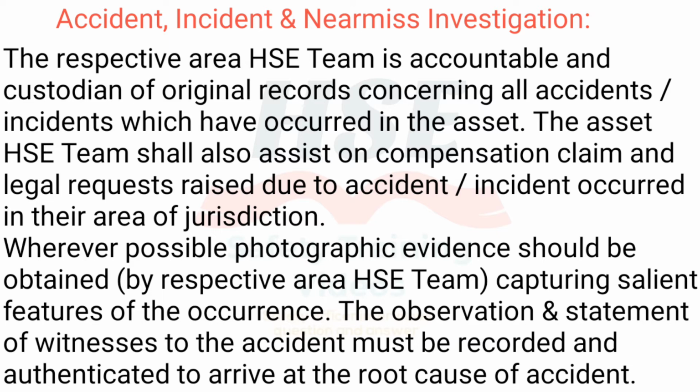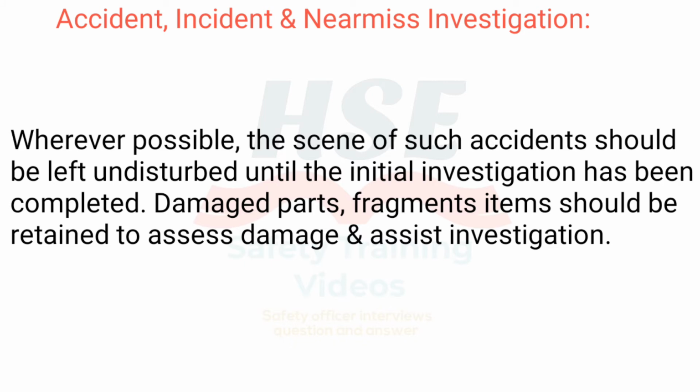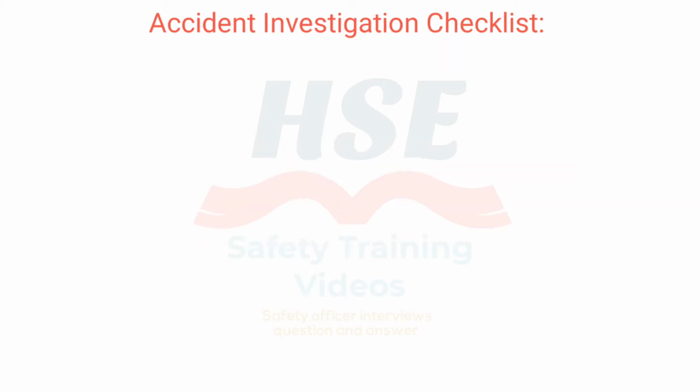Wherever possible, photographic evidence should be obtained, by respective area HSE team, capturing salient features of the occurrence. The observation and statement of witnesses to the accident must be recorded and authenticated to arrive at the root cause of accident. Wherever possible, the scene of such accidents should be left undisturbed until the initial investigation has been completed. Damaged parts, fragments, items should be retained to assess damage and assist investigation.